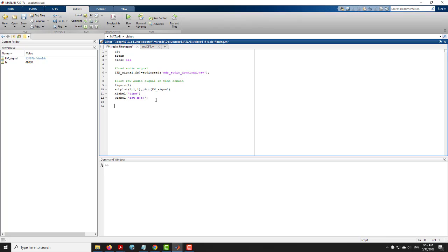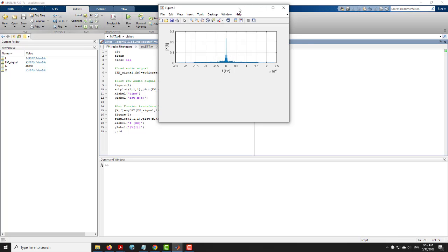To see the spectrum, I employ MATLAB's FFT along with the sampling interval. This is a topic we discuss at length in ENTS 622. I use my own function that retrieves the magnitude of the spectrum and the frequency range for plotting. We'll open a different window to plot the spectrum.